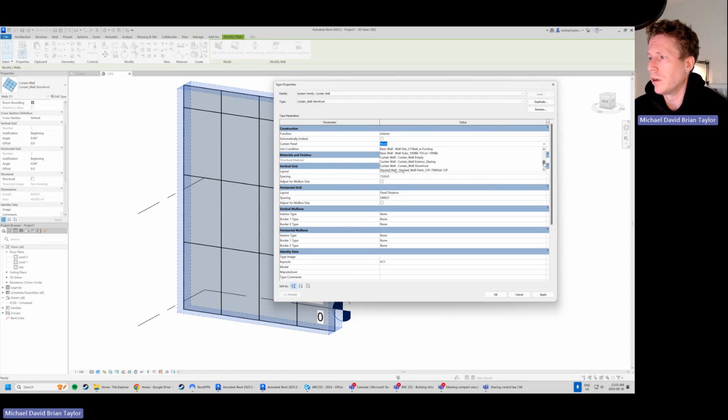getting started in Revit. In your head, you might think, okay, I'm going to set my panel to curtain wall, which of course would make sense. However, what that's doing is it's telling Revit to put a curtain wall within a curtain wall panel, and that's going to double up. It's essentially a little inception, right? So we got a curtain wall within a curtain wall. We don't need to do that. We're just looking at